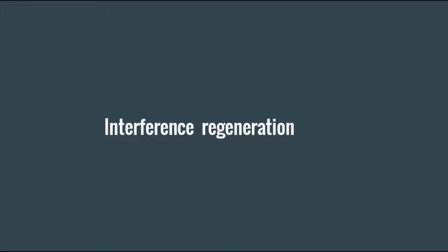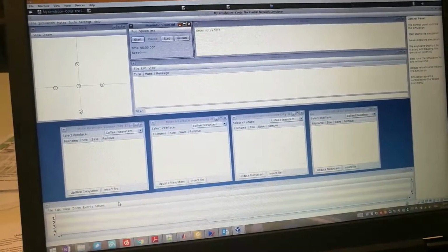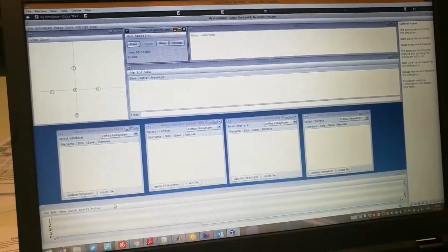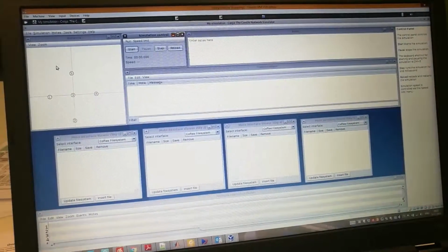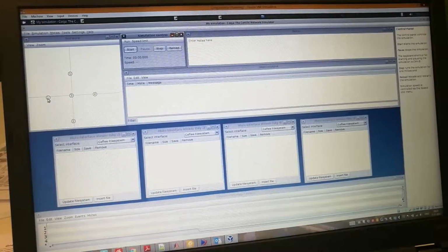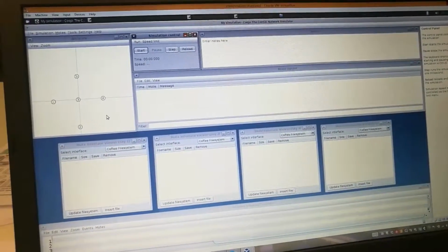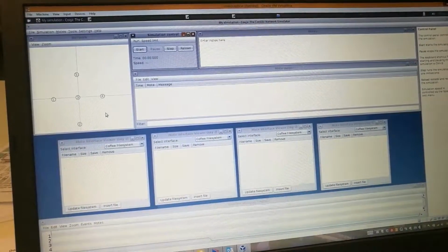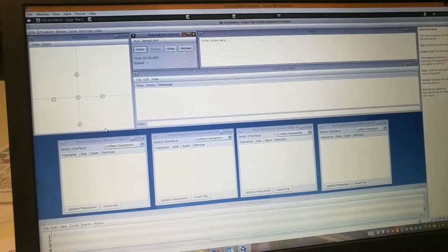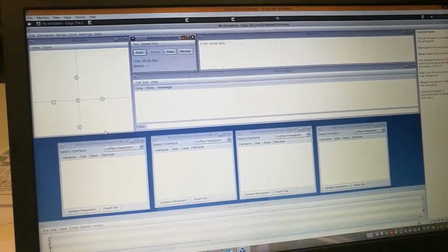From the network window, you can see the topology of our network. One node with RSSI scanner is in the center, and 4 interferers are around it. All of them are assigned to Sky mote. Interferers use the processed dataset as input, and combine with periodic, fixed patterns to generate the interference we want. The receiver with RSSI scanner function is used to capture RSSI value. CC2420 radio has one beneficial advantage that the RSSI value will be shown automatically through the process.